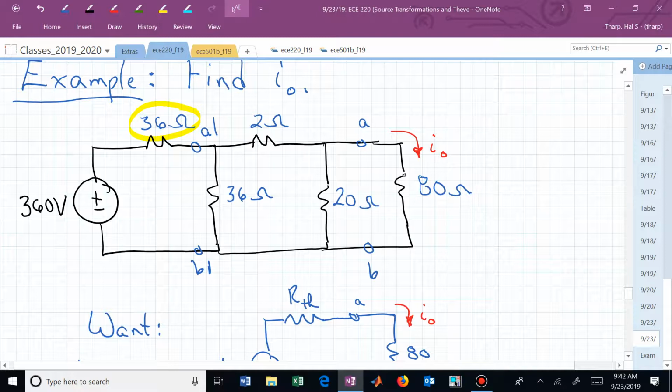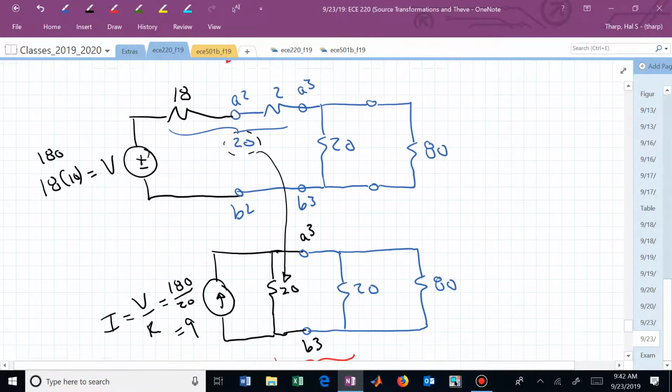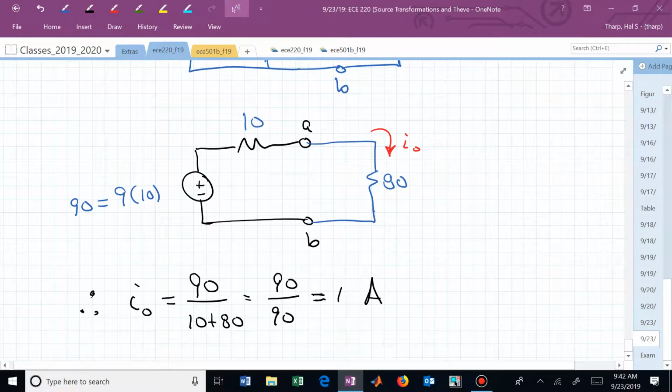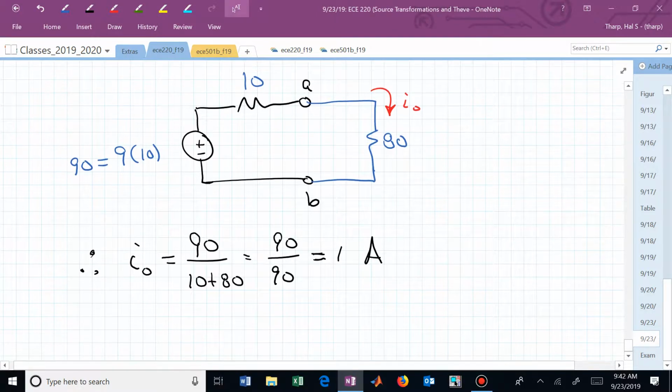3 essential nodes, so you'd have 2 unknown node voltages. So you'd have a 2 by 2 or a 3 by 3 to solve. Now maybe you don't like what we did, but this was kind of easy, wasn't it? Each step was just a fairly straightforward step, and now we ended up with an answer. Let's build that ladder back to what it was to begin with.